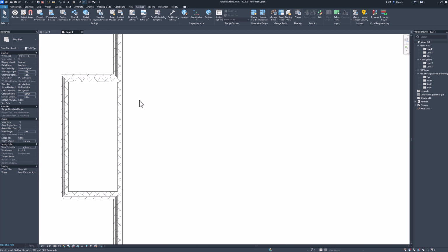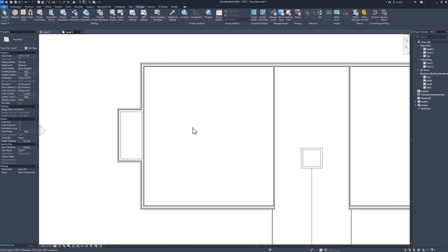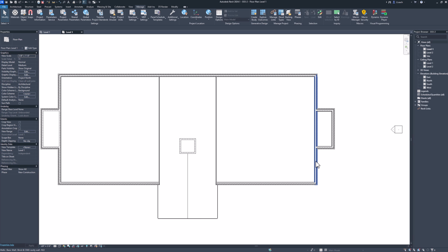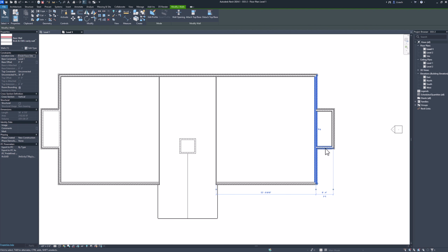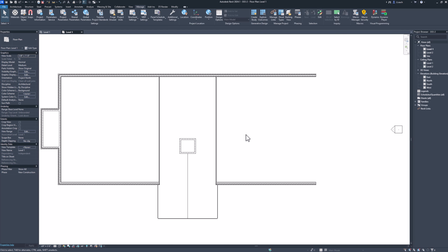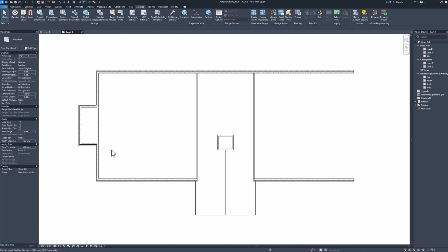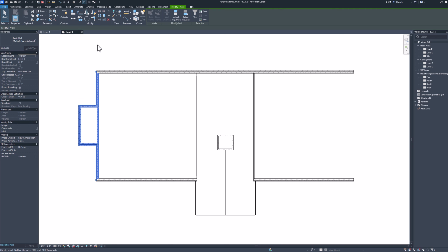Okay, now it says select the 6 walls of the west stair. Okay, so what six walls are we talking about? So we're gonna go over on this other side, right? I want that, and I want to delete these. So those are the walls that we want to get rid of. I'm gonna press delete on my keyboard. So instead of doing the same thing that we did to this side over here, we can just delete that, and then we can select these and mirror this over.